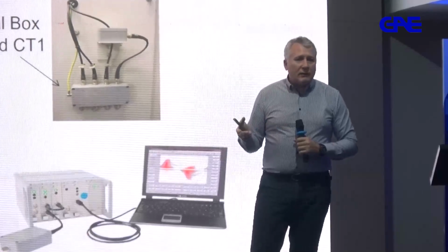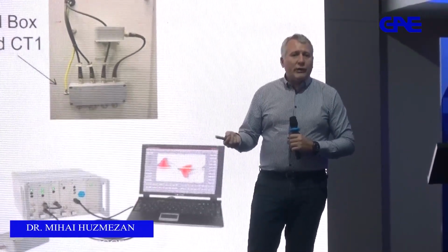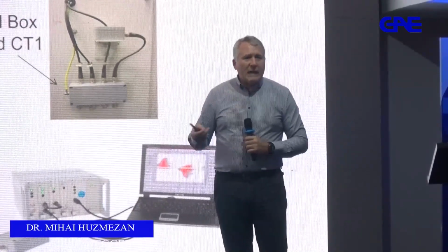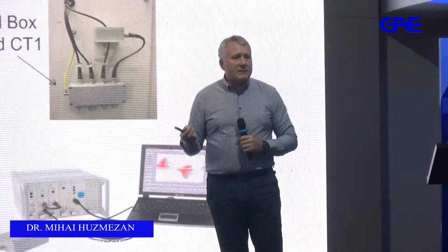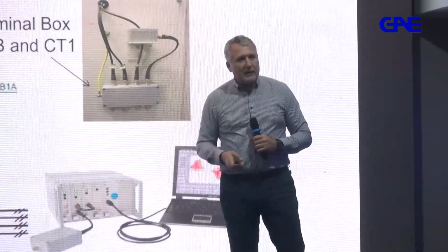Condition-based maintenance is not something that you are not encountering in your day-to-day life. Nowadays you are driving relatively modern cars. They will tell you when you need to change the oil based on how many kilometers, how you drove it, etc., right? This is condition-based maintenance, which in some way helps you save money. If you drive in a more relaxed manner, and you don't drive so many kilometers, you will need to change your oil a bit later in your car's life.